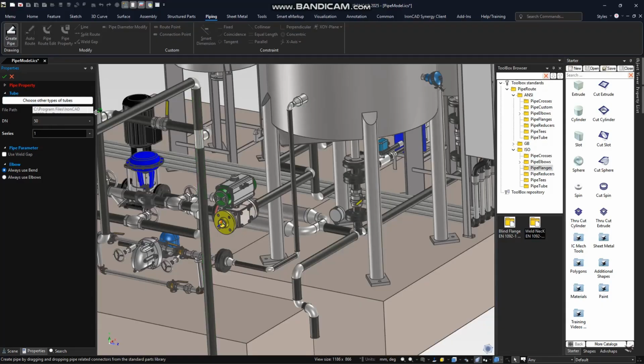You just have to pull this out to see that full path. That's where it's related to. And then you can add certain things like your bends and your elbows. So if you want to use a bend that just creates a pipe using a regular bend, like a sweep bend, if you will, you can use that. Or if you have elbows, you can select that, and you can also choose that.